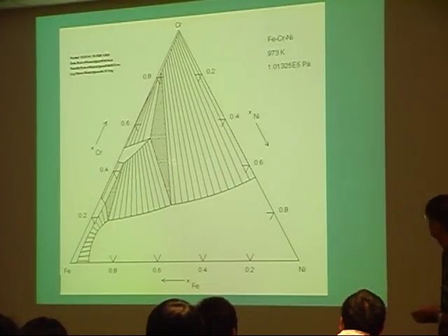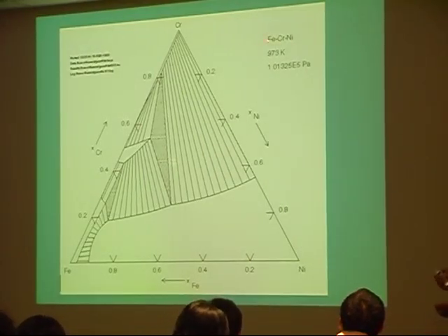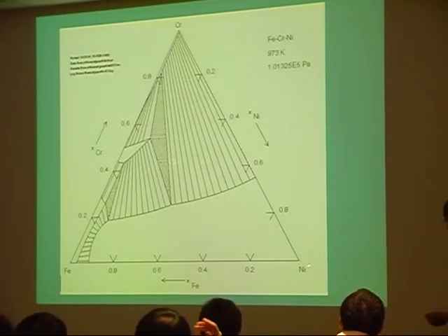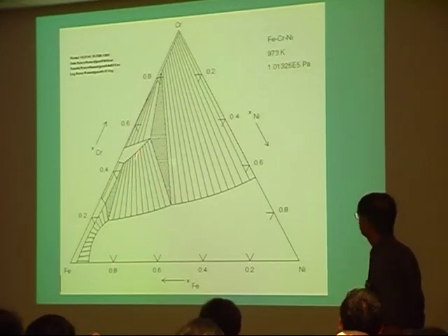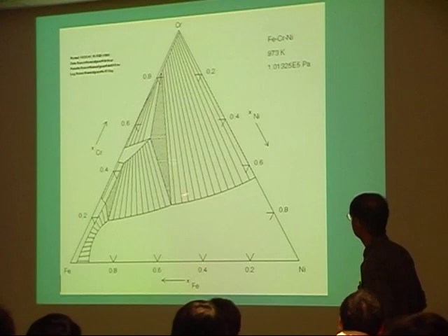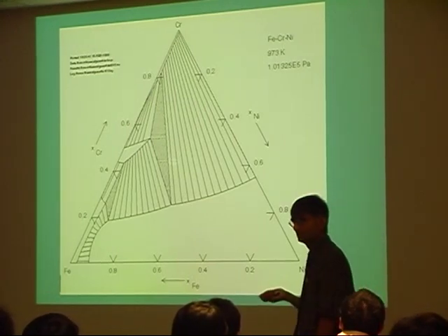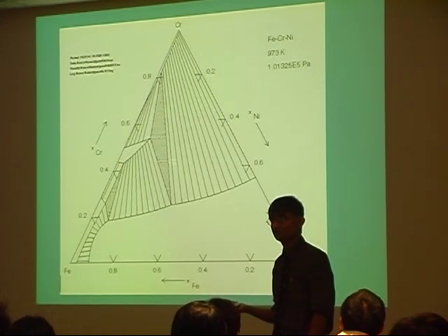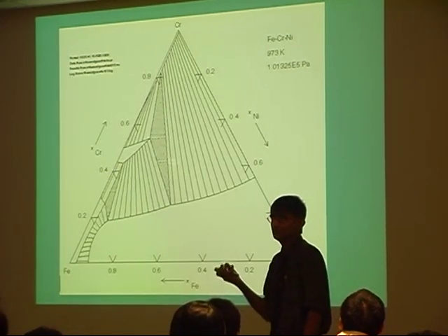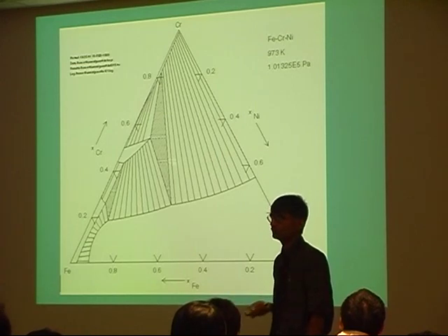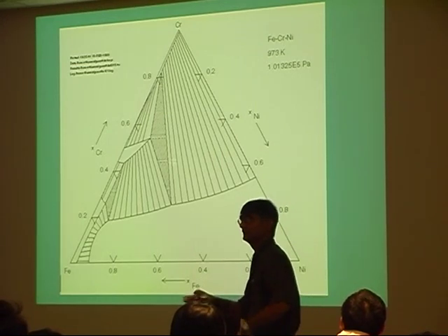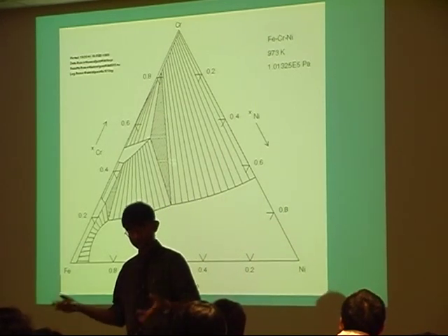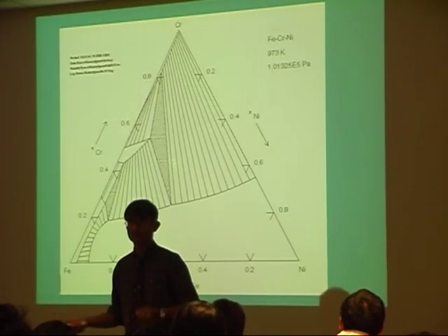Here is an example calculation for the iron chromium nickel system. So this is a cross section of a ternary phase diagram at a constant temperature. And there are many different phases and equilibria between many different phases. And this is what I would call a simple phase diagram. You know, we have only 3 elements in it, but you can have 20 different elements. You won't be able to draw a diagram, but you'll get the equilibrium compositions, you'll get the equilibrium phase fractions from the calculations.